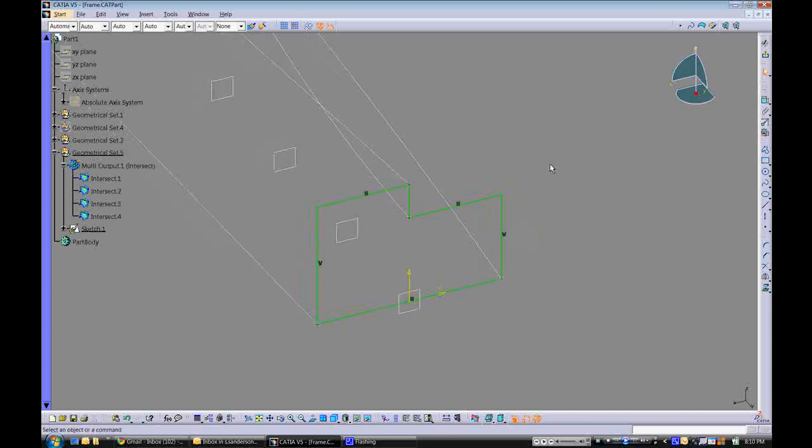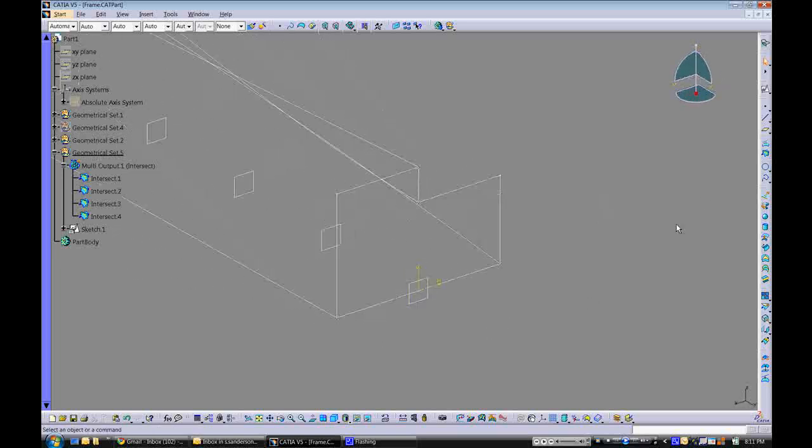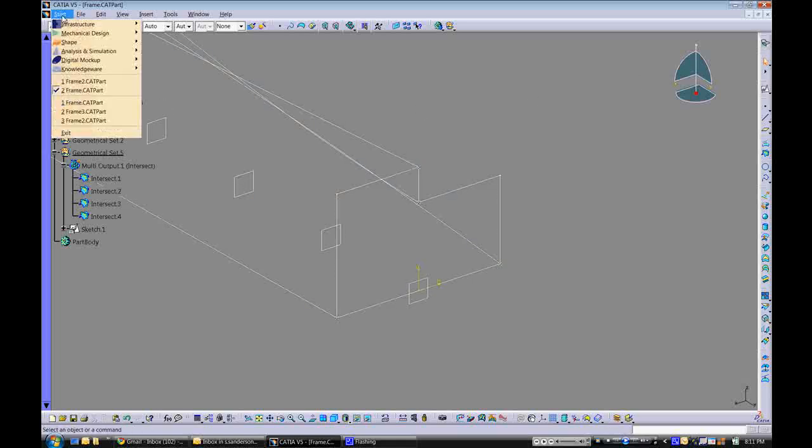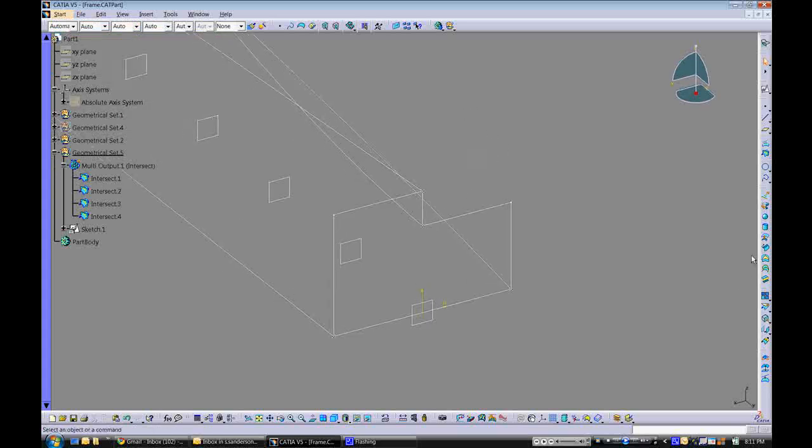So once we've defined our profile sketch, we can exit the sketch workbench by clicking this icon. It looks a little different in Digital Project, but it should be in the same upper right position. So we'll click that. And now we're back out into the part editing workbench, and you can see all of the tools update. In CATIA, I'm actually working under the wireframe and surface design workbench. I think it's called the part design workbench in Digital Project, but the tools should look like this.